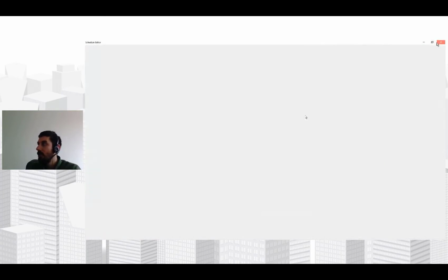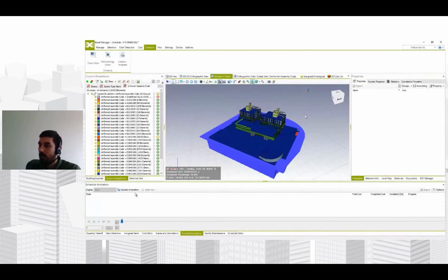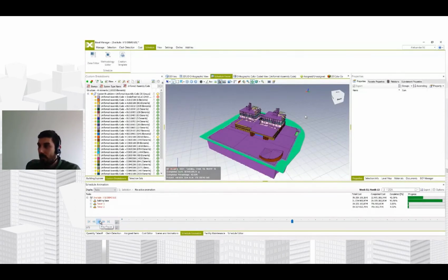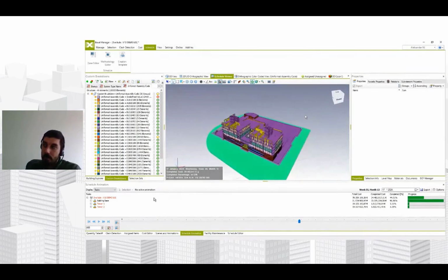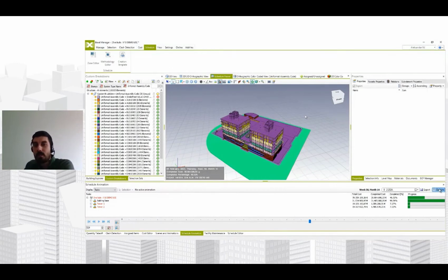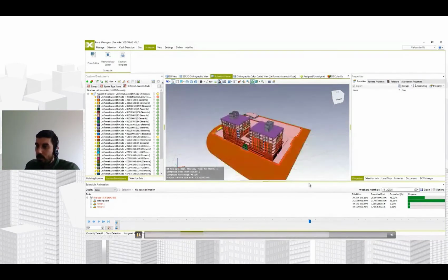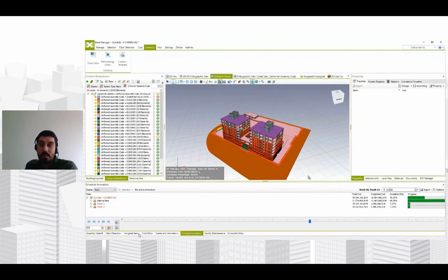So you can see the different color coding for different values, and you can also visualize it in 3D in the cost class in the schedule animation. So you can visualize, let's say, if you have the actual schedule, you can visualize CPIs, SPIs. You can see which parts of the structure are, let's say, green with the good CPI, which are red with the bad CPI, and things like that.